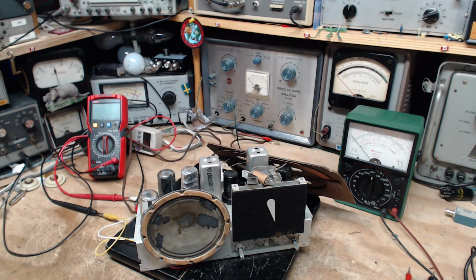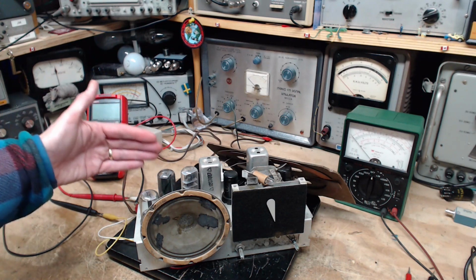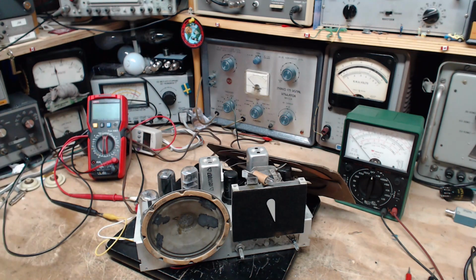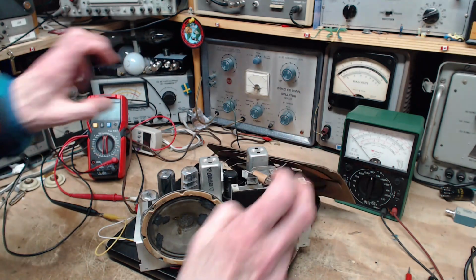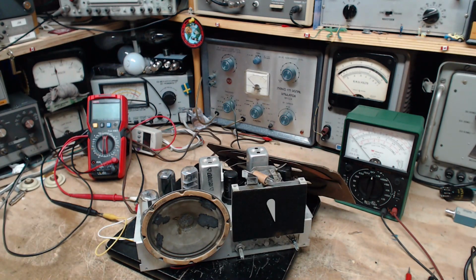It wouldn't be electrons fighting in because it's going positive a little bit. Or the capacitor I put in does leak a little bit. I don't think so. I don't think it has any propensity to leak at all. So it could just be a tube factor. Now when I changed tubes, that little voltage changed. And if it is the contact voltage, then it might vary from tube to tube.